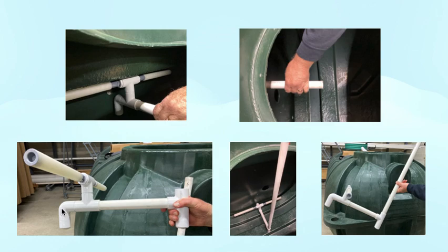And then it's also extended out so these diffusers aren't right up against the wall here in the tank. And then what you're going to do is kind of hand measure, because you want your diffusers right up against this partition of the tank, but then you'll want to have it extended out so that when you connect your airline, you'll be able to reach in there through the riser lid. So you'll eyeball how much pipe you need, and you'll attach that to the end of this T and connect it to that other pre-manufactured piece.